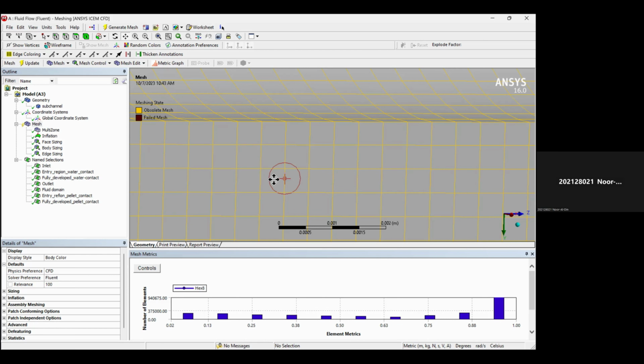So during grid independence test, we have to increase the number of the nodes or the cells, and then check whether my solution varies or not, right? Yes, sir. I said about it earlier. So how will we increase the number of the nodes? You will decrease the element size, and thus you will increase the number of the nodes or the cells. Have you got it? Yes, sir.